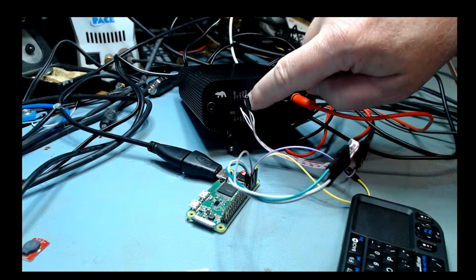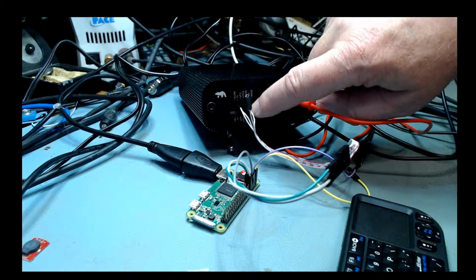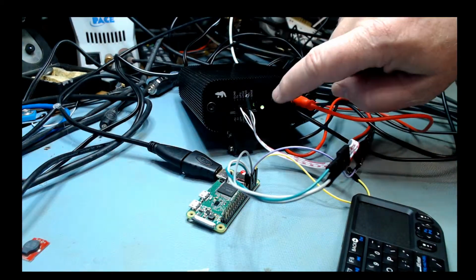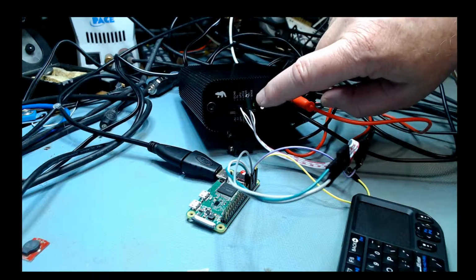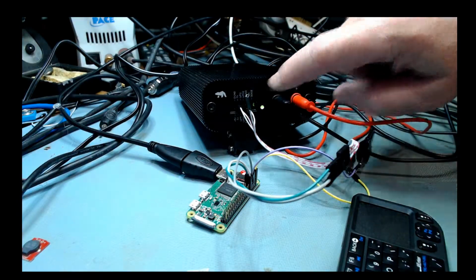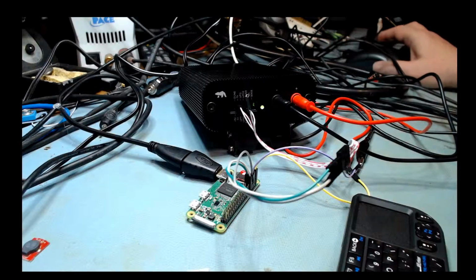You've also got GPIOs, inputs and outputs. You've got a normal analog input, and another analog input that's 0 to 5 volts, and another one which is designed as a sense across, for example, an external current shunt. If you want to measure a secondary supply, like the 3.3 volt rail or something, you could break that out.